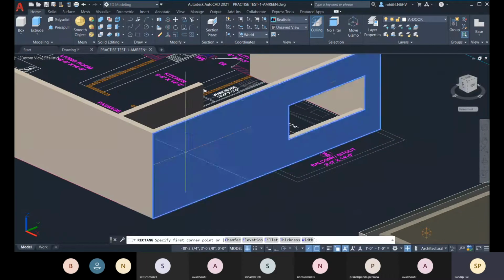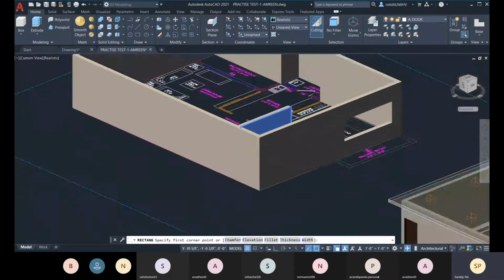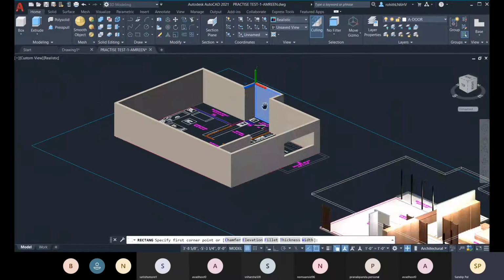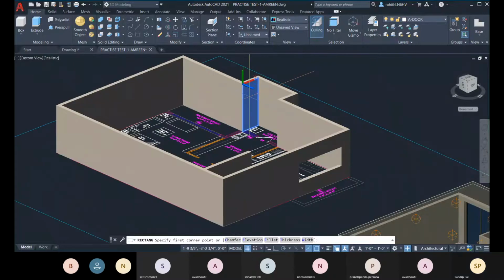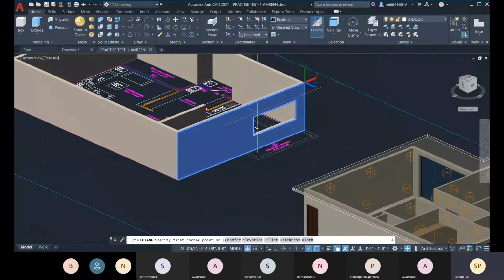Right now, if you go to create any object, you can choose any face of any object, and as per that face, it will be the working plane. You can see your UCS icon. This is the XY plane, and this is the Z direction, right? So your UCS will work dynamically.